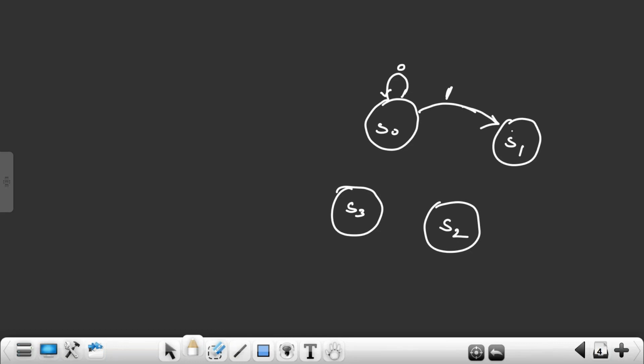So S1 state means pin entering state. It is pin entering state. If pin is entered, go to next state. 1 means pin is entered. If pin is not entered for 5 minutes, then go back to what state? Reset state.